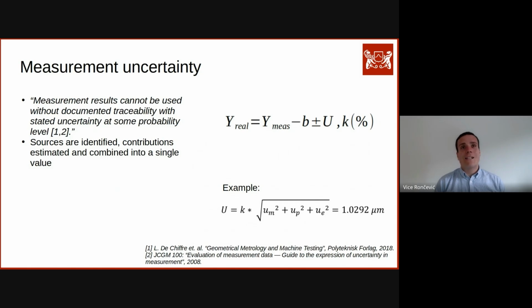Yes, I can say, not really accurately from the top of my head, but the uncertainty here that you can see is actually a CMM uncertainty. So plus minus 1 micron is a CMM uncertainty with a very small ruby probe. This is not something that you can achieve with the caliper. A caliper would be at least 10 times this. Yeah, so at least 10 times in the best case scenario. And the reasons are of course many.